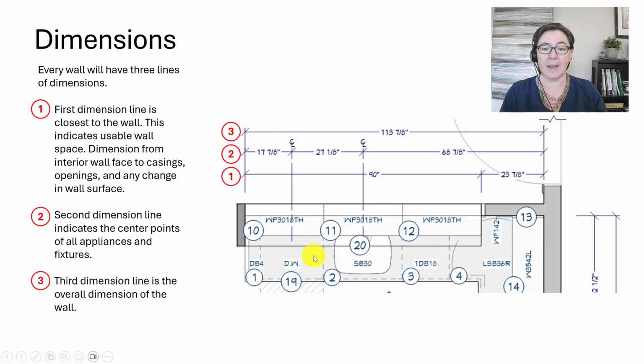Now, I do recommend, and it's shown here in this drawing, that once you place this center line dimension, which typically, whether you're using Chief or AutoCAD, you snap to the back of whatever piece this is, you go ahead and grab that line and pull it down to the center of your elements. This makes it way easier to read and to tell exactly what is being dimensioned. You can see that again here with this one. Notice that your center line measurement is using a center line type, and it's got the center line symbol.